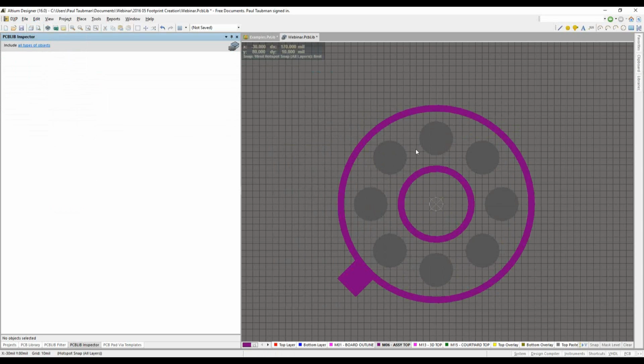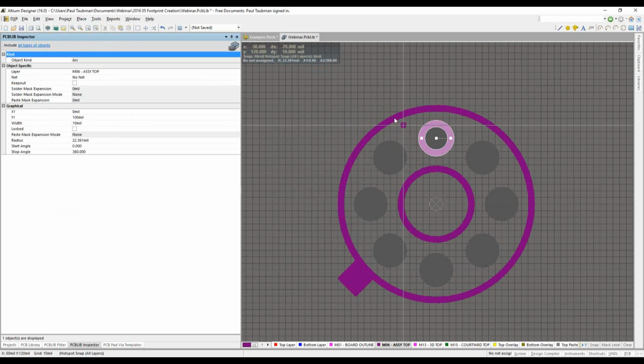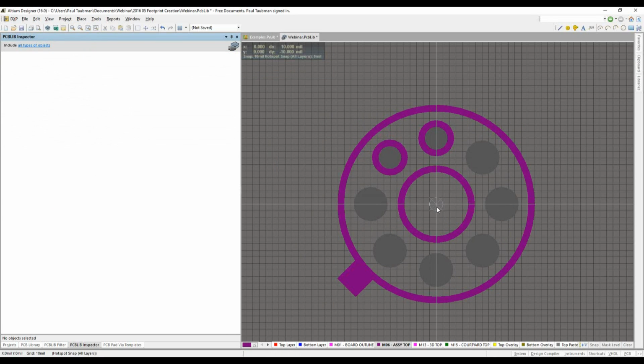As for the circles here, obviously they're through holes, so I'll have to draw those in. But again, I'm just going to take advantage of the copy and paste. So I'm going to go into Place. Here's my full circle. I'll put this in over here. And from there, I'll do a Control C since it's already selected. All right, and I'll just Control V it and just do this very quickly. Again, doing Control V followed by the space bar, then clicking to lock it down, Control V, space bar, lock it down, and we'll do this again, and there it is.